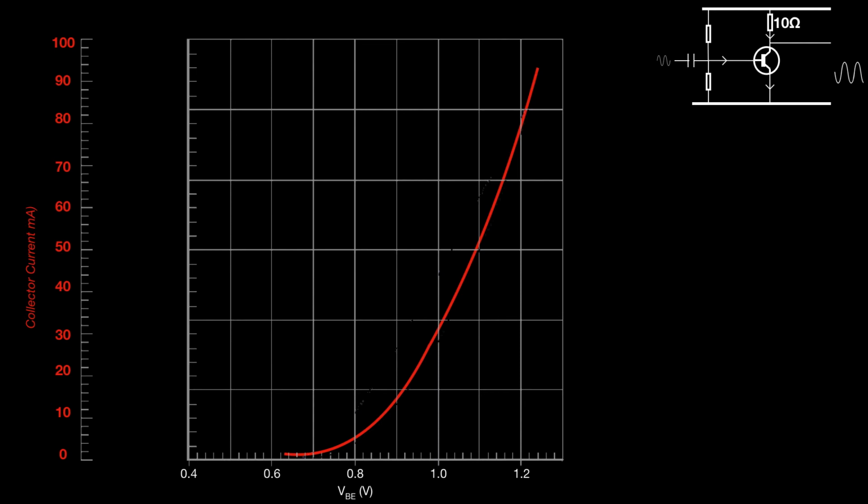It doesn't really move into being linear till perhaps 0.9 of a volt. So we talk about this curve having 2 parts, the nonlinear part, which is before the knee, and then the fairly linear part, which is after the knee. And on the right at the top of the screen, we've got a reminder of what the circuit might look like.